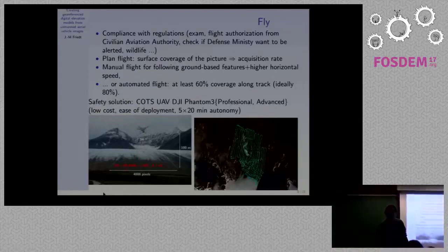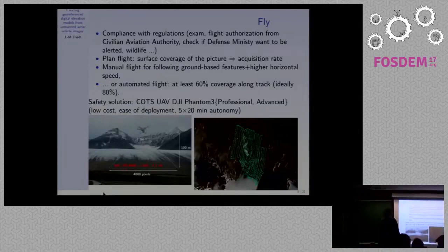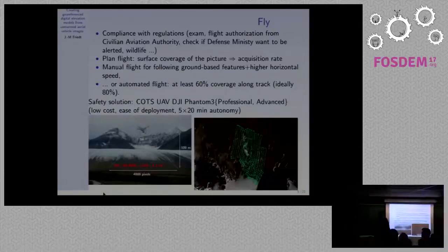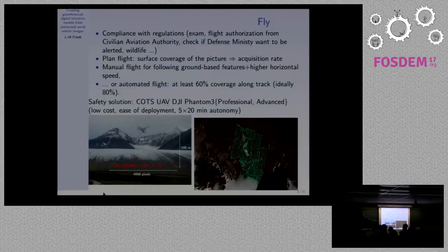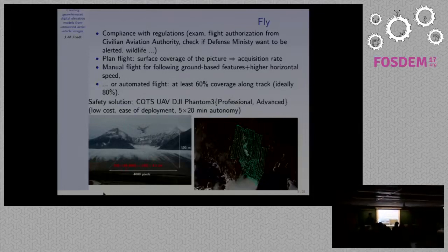I tried to do this a couple of years ago, and we ran into trouble in the mountains with too much wind to fly a drone reliably. Did you just find the right kit that works? So I have flown here with winds up to 25 kilometers per hour. Sorry, the UAV can fly up to 10 meters per second. So above 2 to 3 meters per second, I would not advise flying.